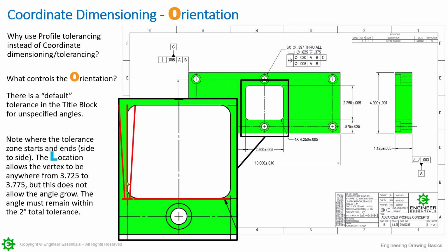tolerance to. If you're like me, I've had to inspect angles my whole career. I would much rather inspect either angularity or even better, profile the surface. Much easier for me to inspect because I don't have to deal with angles at all. But with this type of tolerance called out, you do have to deal with angles. You have to measure that angle to see whether or not the surface came in. This means for a lot of you out there that are machinists, you're going to have to do a little bit of a trick here and find out where your values can be whenever you go in to take your dimensions, because you're probably not going to actually inspect the angle. You're going to mathematically figure out where that angle is.